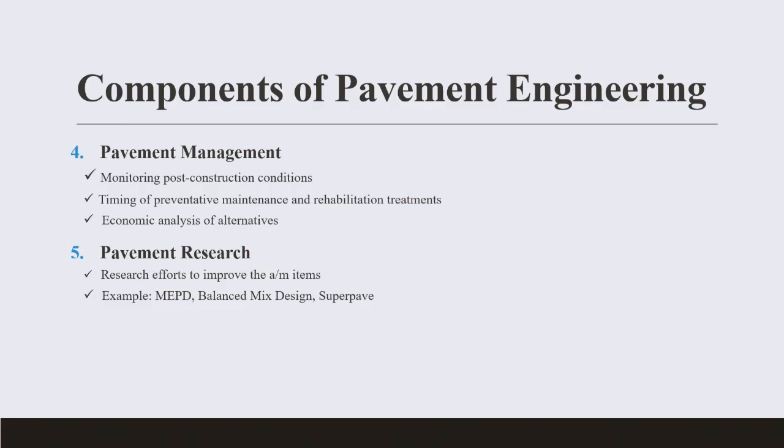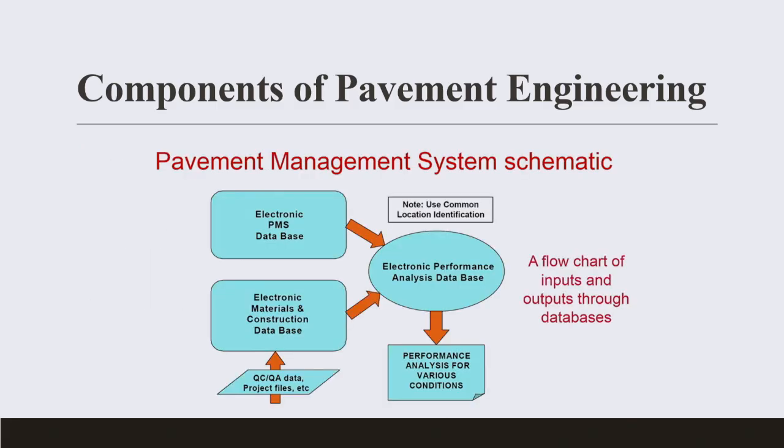And new properties, once you develop new material, all this has to be updated, whether the MEPDG, Young's modulus, Poisson's ratio, gradation, right? So all this is going to change, so it has to be changed in your software, dealing on a project level or on the holistic approach or the network level, which is the asset management system or the pavement management system.